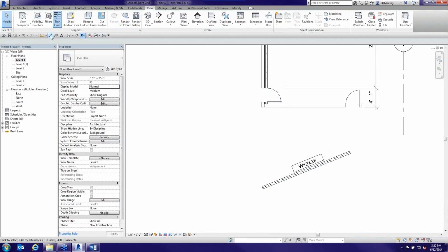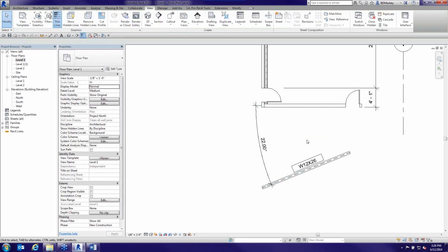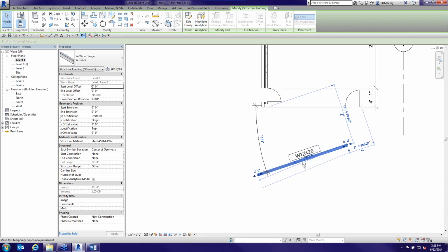The other thing that I love when I'm getting into things like this is the formulas also work for angles. So if anybody's drawn a line or drawn something like, man, I need that to be at a 4/12 pitch or a 3/12 pitch or whatever pitch it's going to be, what's great about this is if I have an angular dimension, I can click this angular dimension and say, oh, you know what? This is going to equal the arctangent of the rise divided by the run. So I'm changing 4/12 into an angle as opposed to a number to really get me what I needed to do. So I can come in here and say, okay, look at this. I'm just temporarily going to say arctan, boom, now I've set that to be my 18.43 degree angle.